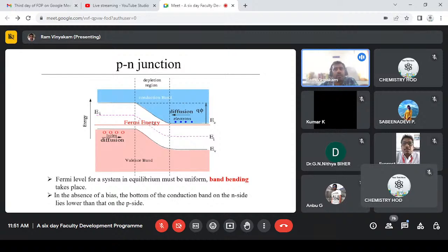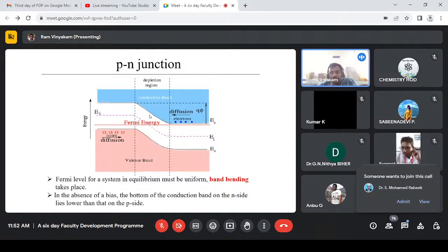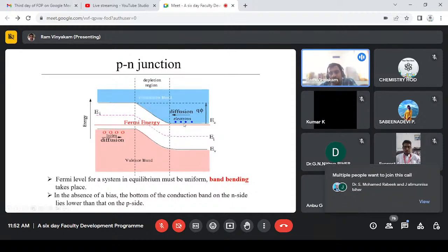So the arsenic ion will be positive. When the holes move from the p-type to the n-type, the positive ion will resist or oppose the movement. That region of ions is not moving; they are substituted ions in the lattice, present at the interface, and form the space charge region. That will create a potential in the space charge region, which we often refer to as the built-in potential at the junction. This built-in potential can be understood in terms of energy levels too.